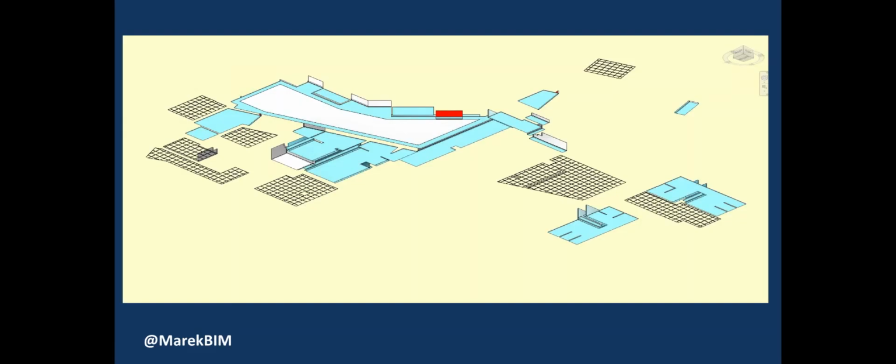So as you can see, we have our ceilings, we have our grid. Also, you can see where we left the drywall and specialty ceilings as just a chunk, a space, a 4-inch block. Once again, we don't need to put the framing in as it is fluid and can move. Acoustical ceilings obviously have to keep the 2x2 or 2x4 design.